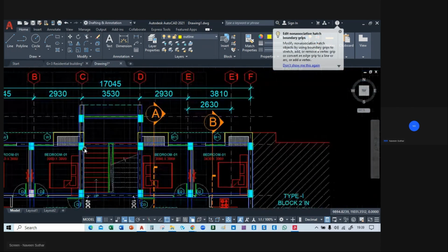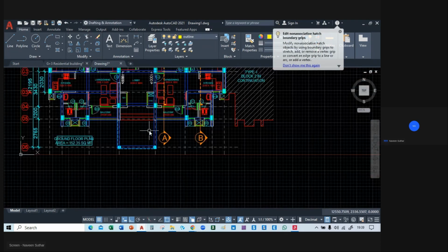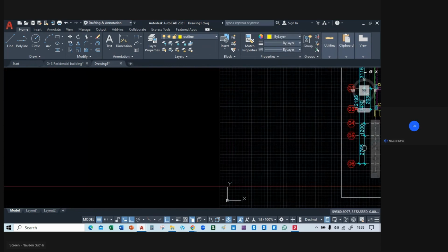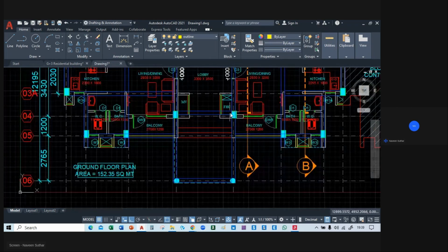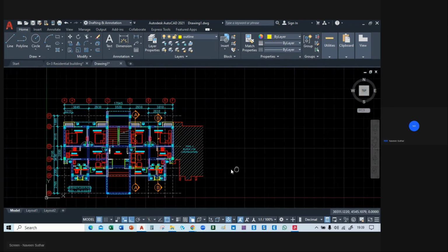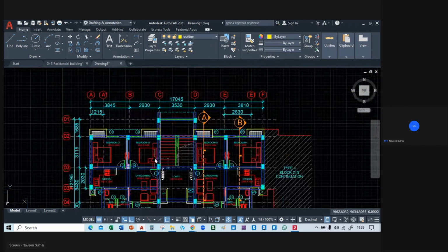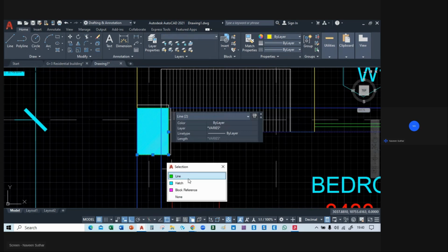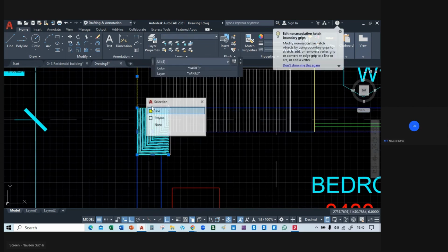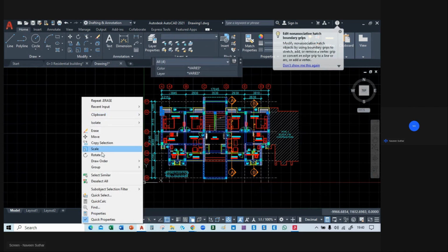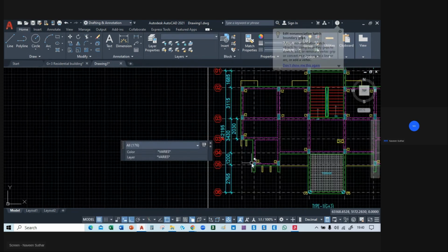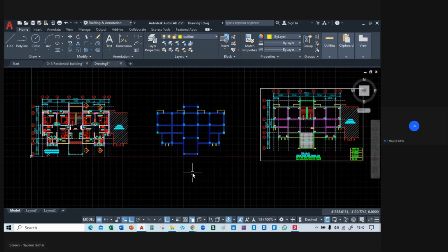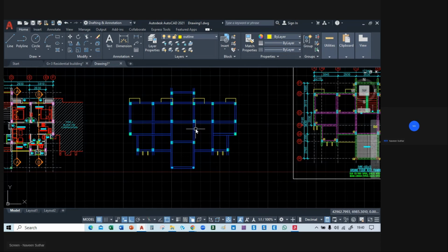And I think this is the new one. Okay, so terrace here. This one is a terrace. Okay, so we'll select the beam line, column line, hatch, and outline, and go to select similar, and we will move this from here to here. Okay, so we got everything.